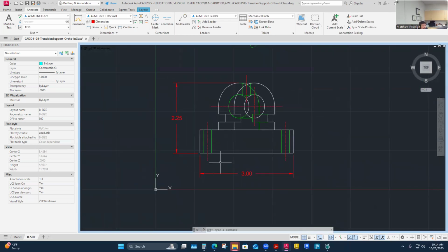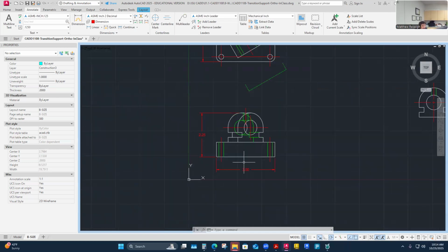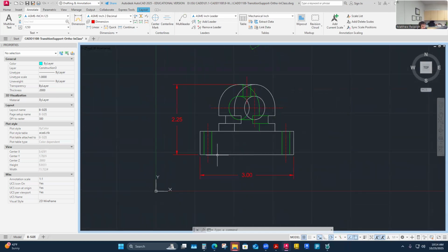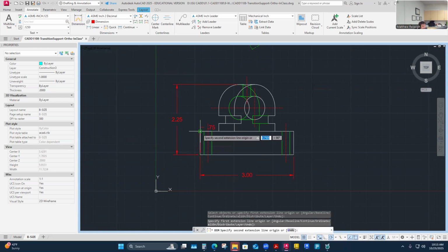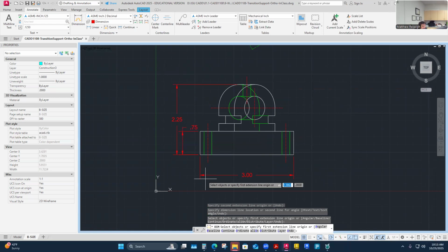I'll start with the rectangular base. I do like this as a datum right off the bottom. This nice flat surface, the way we positioned it in its stable part position, draws me to this being a nice controlled datum surface to pull from. So I'm thinking about just that part width, and height, I should say, is this one. Seems critical.